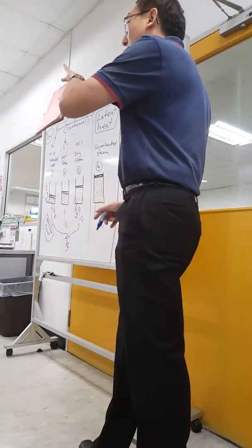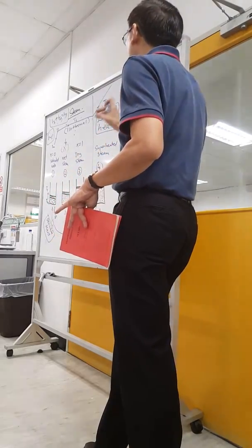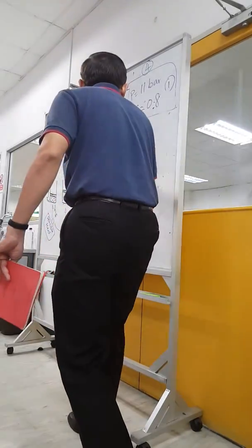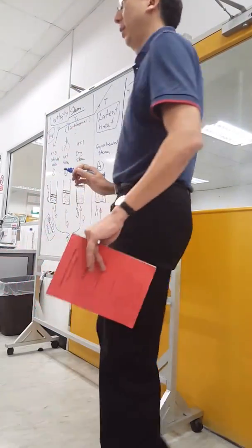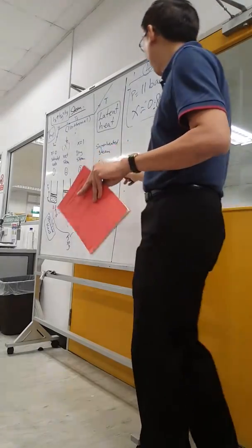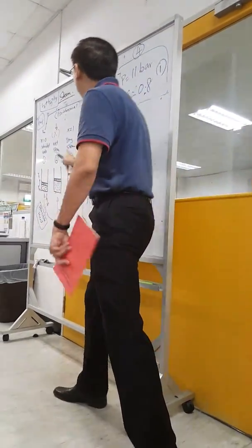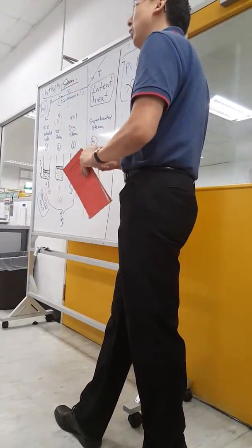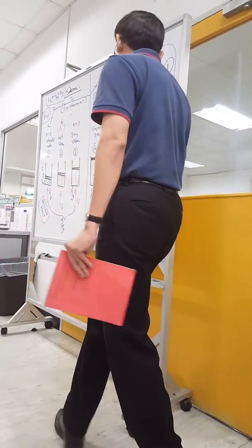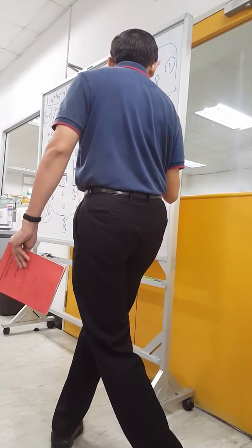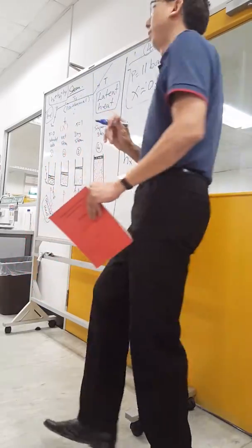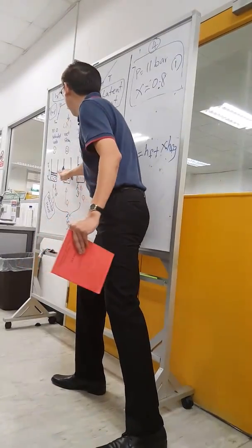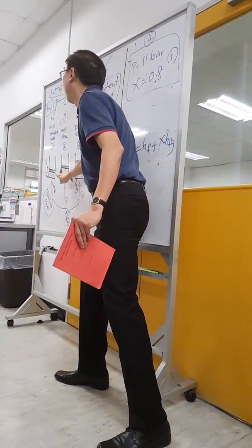So in your book, to denote stage 2, they call the total energy inside here Hx. So this is the total energy with a dryness fraction, stage 2. You notice that only Hx has an equation. What is this? Hf plus x times Hfg.